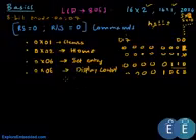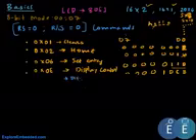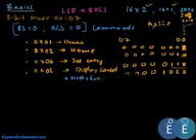Alright, so the next command is display or cursor shift. With this command we can shift the entire display or the cursor, and as you could guess, the one shifts here, and this bit is called S/C. C stands for cursor here, and S stands for shifting the display itself.